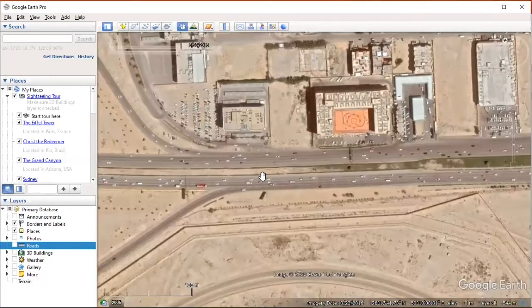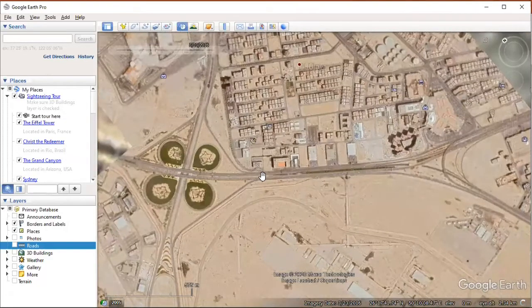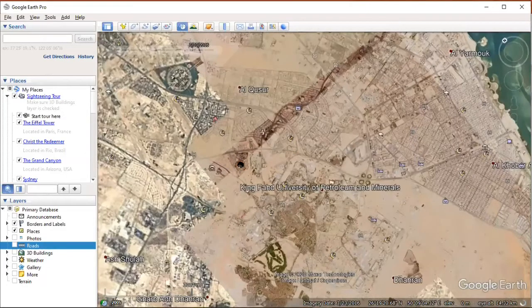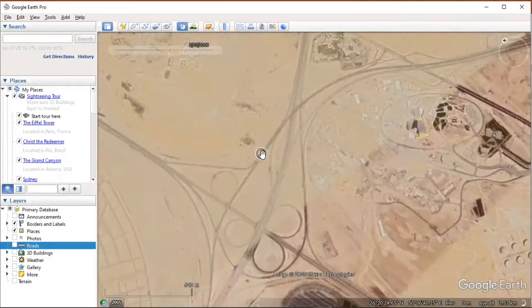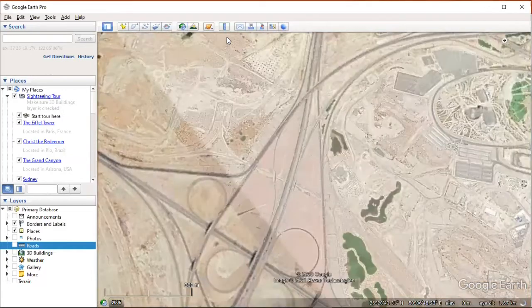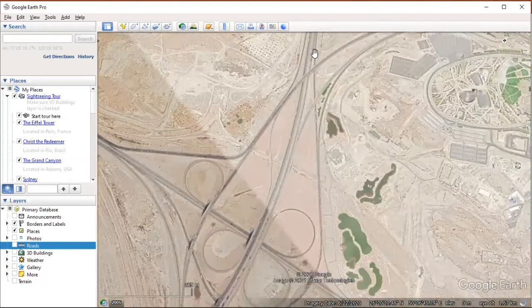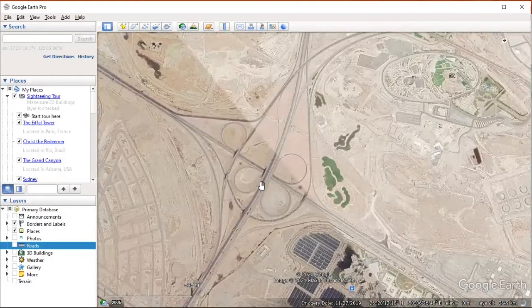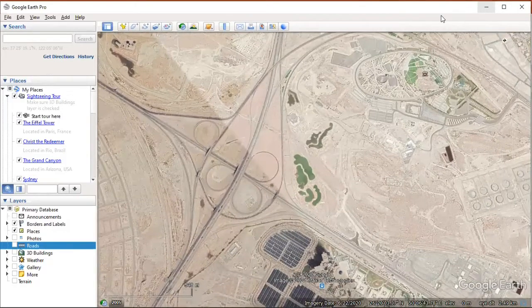We can have a look at it. If we look at here, for example, this site has multiple weaving. You have vehicles coming from this side, they are exiting here, and vehicles coming from that approach merging here. This is multiple weaving segments integrated together. And for example here we have traffic coming from that side going to that side. It's different. The Highway Capacity Manual method doesn't work for these kinds of complex weaving segments.